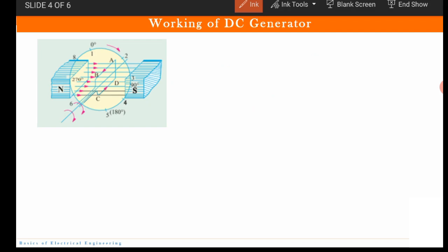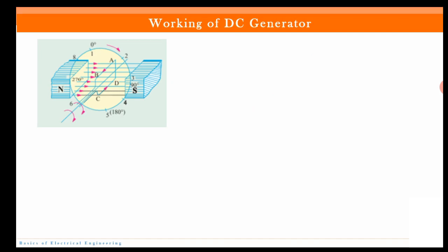Now let us rotate the coil to position 2. Now when it turns slightly, flux linkage is there. Now also the magnetic field lines pass through the gap which is there in between the coil. But since we have tilted it, we have rotated it, now our conductor starts cutting the magnetic field. It means now there is rate of change of flux. Fine. So due to Faraday's law of electromagnetic induction, EMF is produced. Okay.